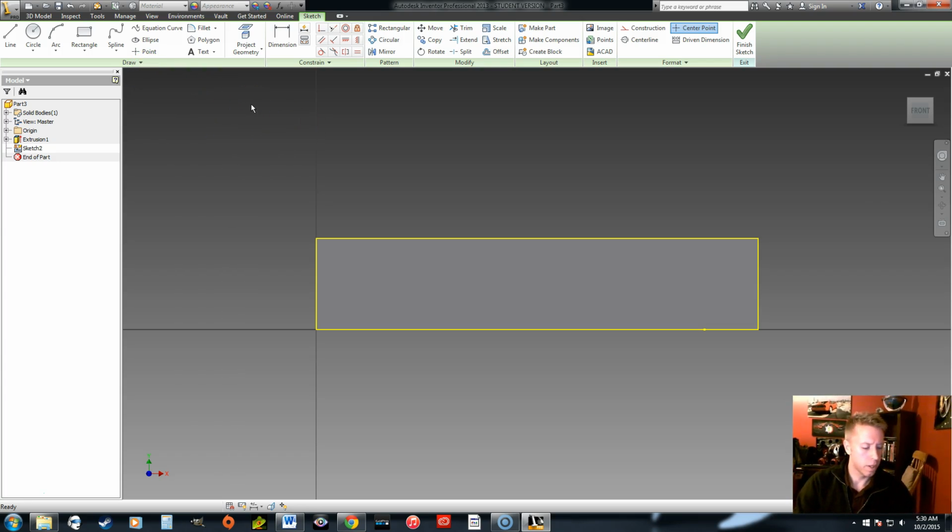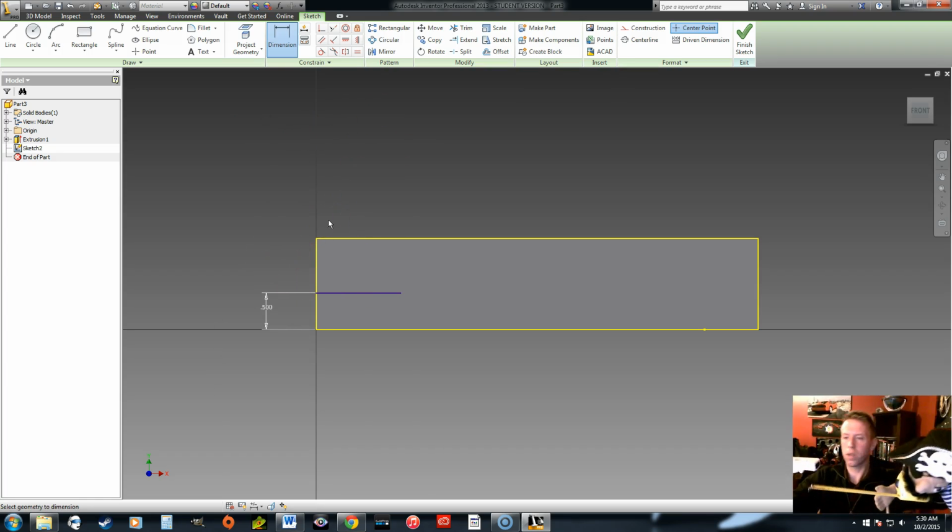I already need a measurement here. About how deep is that cut? Looks to be about a 1/2 inch. So what I can do is put a line here. I'm going to cut in. It's a 1/2 inch up. So I click the dimension tool, 0.5, and then we're going to measure. Again, we're being really rough right now. We normally want to be more precise.